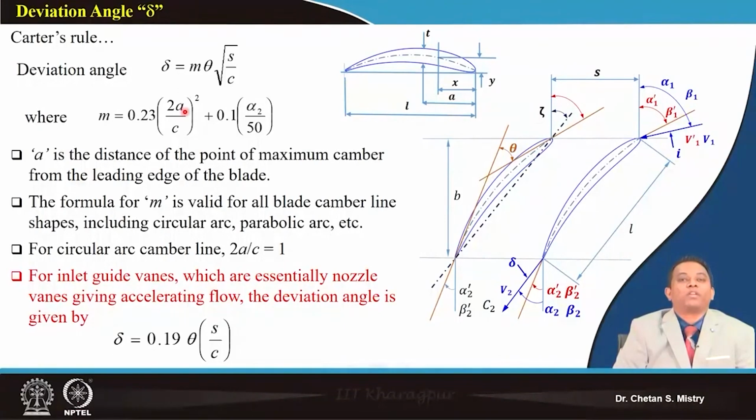Based on flow visualization, Cp distribution and detailed flow field study, people are modifying this deviation angle to make the flow be in line with what we are expecting. So the use of computational tools is helping us in deciding this deviation angle.